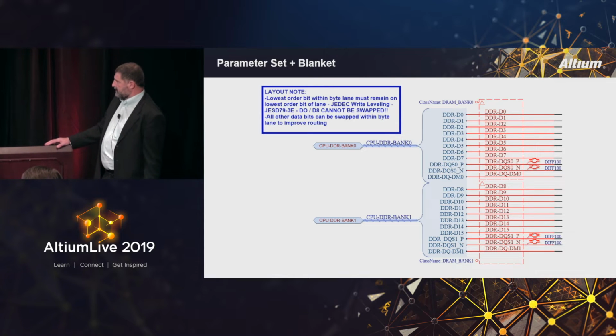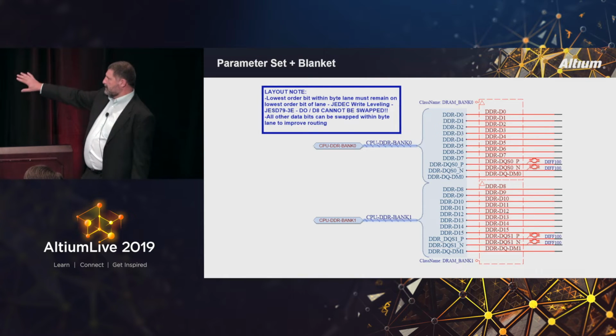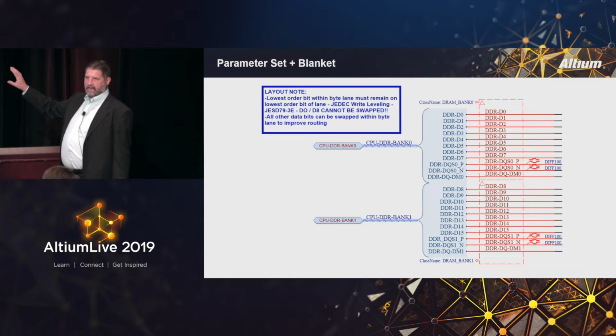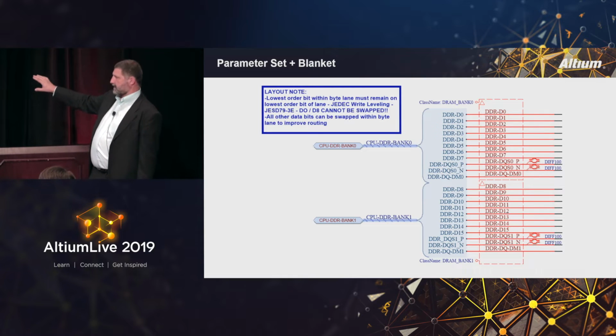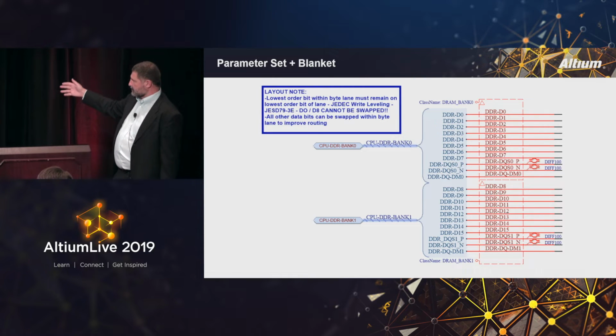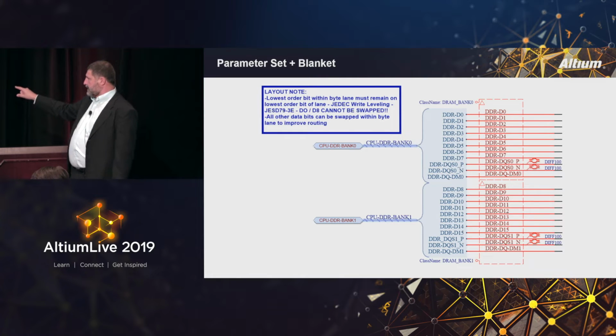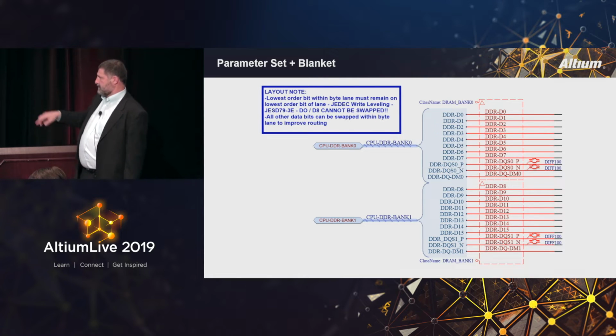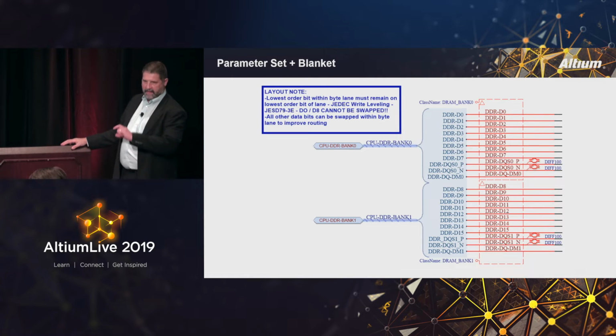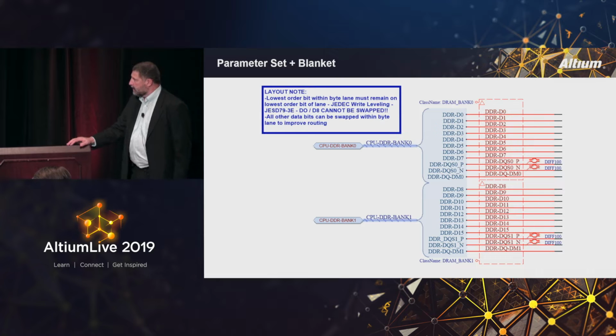All of the nets that are in that box are going to be in that class. You don't need the wires in order to have the class. You just need the net name. We show it here with the class. The other thing you can do is put it at the end of the wire, and if the blanket encompasses that, it's also going to pick up that net.